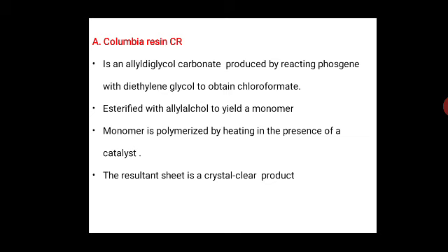Along with this, the material is brittle, which makes it difficult to work by milling operations, but it can be readily machined by routing, and a high quality photoelastic model can usually be produced within an hour.